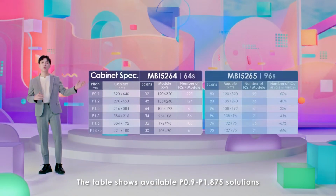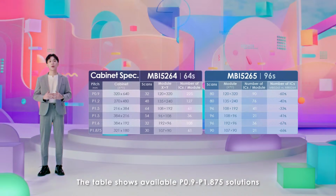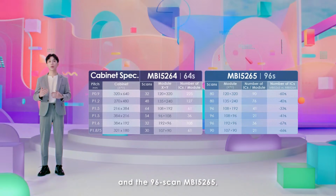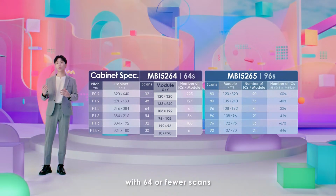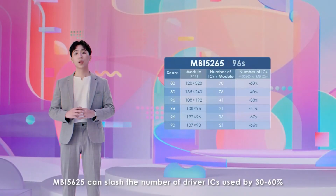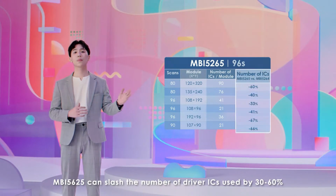The table shows available P0.9 to P1.875 solutions. Comparing solutions based on the 64-scan MBI5264 and the 96-scan MBI5265, when the X or Y axis of the modular resolution is a multiple of 64 to 96 scans, MBI5265 can effectively replace existing products with 64 or fewer scans. MBI5265 can slash the number of driver ICs used by 30 to 60%.